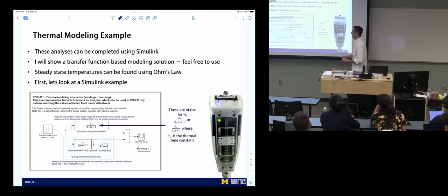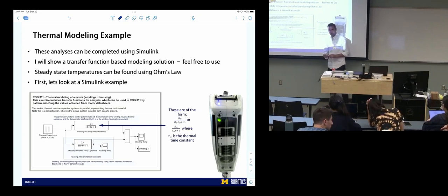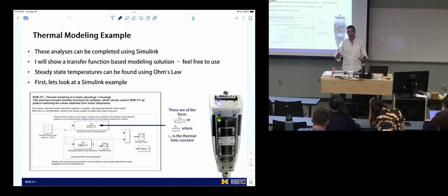What is this? Can you guys read this? Yeah. Isn't it simulating the temperature that the entire motor is going to get, if we're estimating its resistance for the convection and the conduction? It's going to simulate the entire heat of the windings and everything. Simulate the temperature rise.